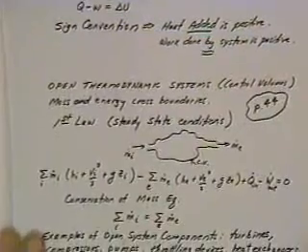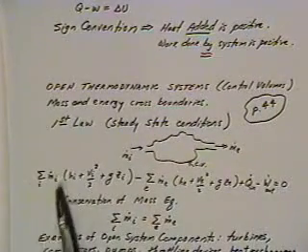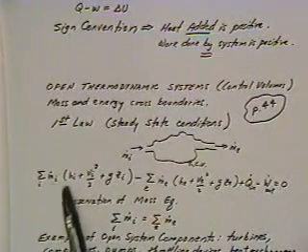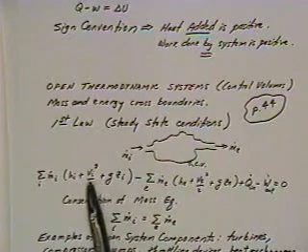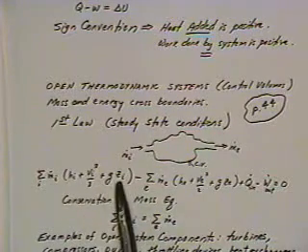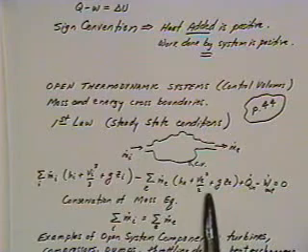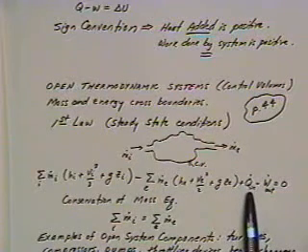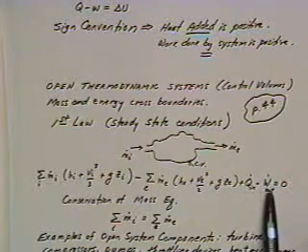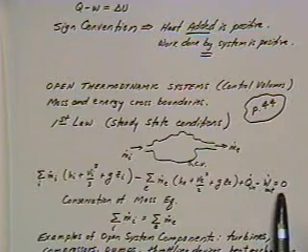and so the complete formulation of the first law says that all of the enthalpy, all of the kinetic energy, and all the potential energy changes for our system, plus the heat transfer into the system, minus the rate of work out of the system, is equal to 0.